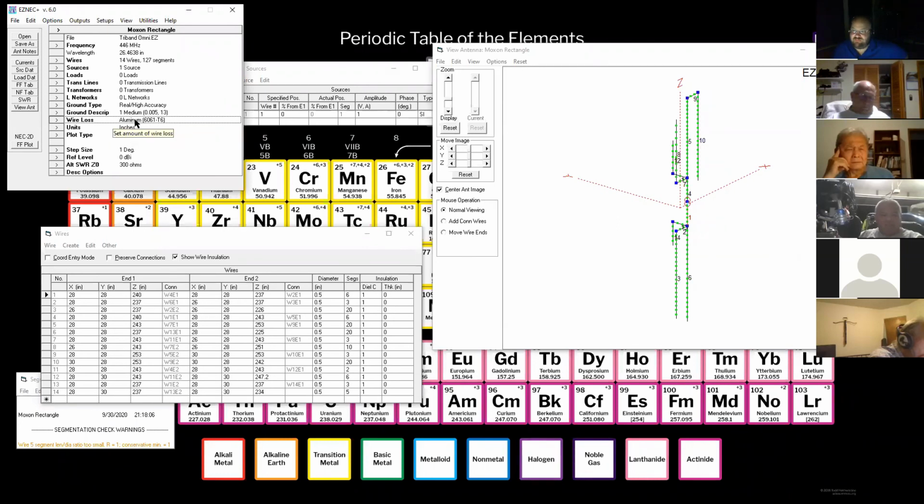My personal favorite for building HF wires is copper-coated stainless steel, which is really hard to get your hands on, but it's got the strength, it's got the corrosion resistance, and it's got the conductivity because of the skin effect using that copper. So I would choose the wire that you're intending to use. If you don't know what you're intending to use, just use the middle ground of aluminum.